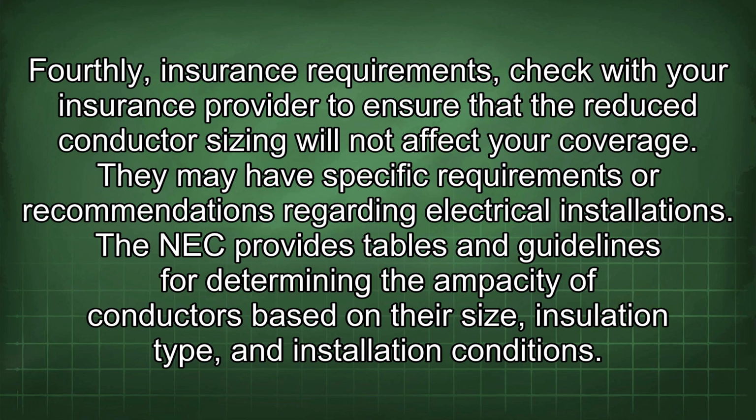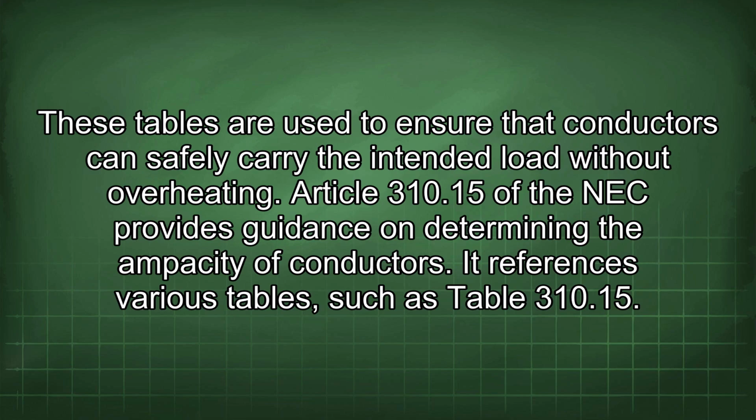The NEC provides tables and guidelines for determining the ampacity of conductors based on their size, installation type, and installation conditions. These tables are used to ensure that conductors can safely carry the intended load without overheating. Article 310.15 of the NEC provides guidance on determining the ampacity of conductors. It references various tables such as Table 310.15(B)(16),